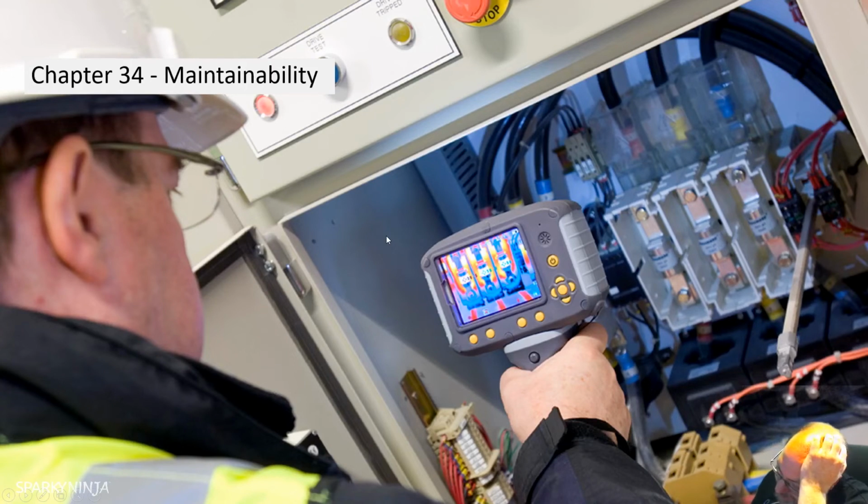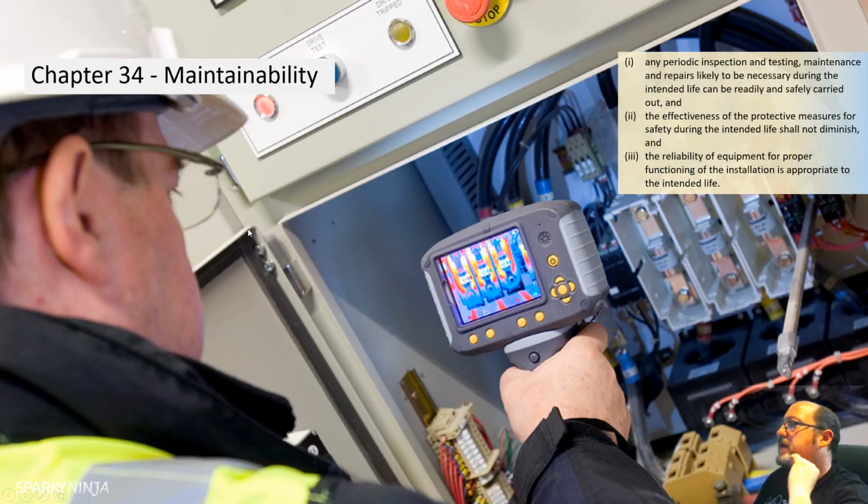We then have maintainability, 34. Assessment will be made of the frequency and quality of maintenance the installation can reasonably be expected to receive during its intended life. The person or body responsible for the operation or maintenance of the installation shall be consulted. Those characteristics shall be taken into account in applying the requirements of parts 4 to 7, so that, having regard to the frequency and quality of maintenance expected, any periodic inspection and testing, maintenance and repairs likely necessary during the intended life can be readily and safely carried out.